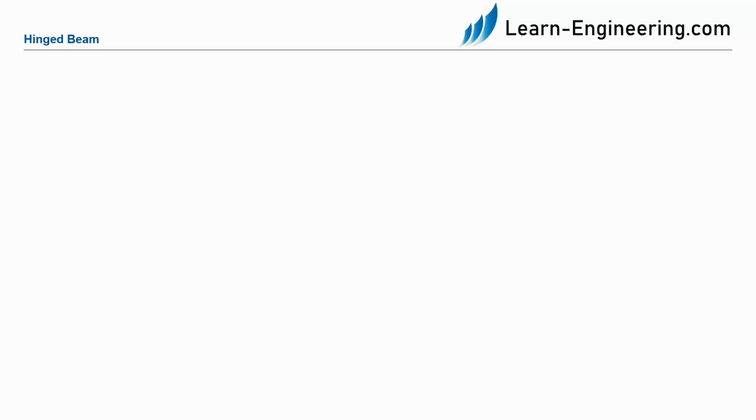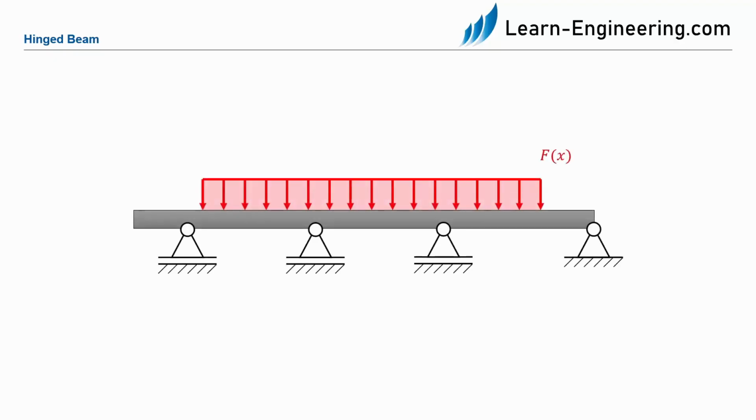The following is a body which is very elongated. Since this body has a great length, it must be supported by several supports. To avoid strength problems, we have a hinged support at the one end and the remaining supports are simple supports. Even though we are working with rigid bodies in statics, we should keep reality in mind. The system now has 5 support reactions with the 4 supports, so we have a statically indeterminate system again.